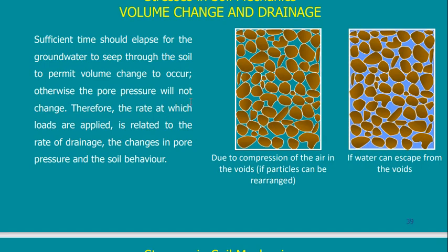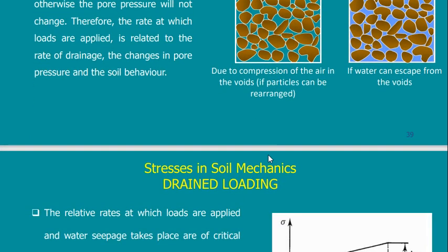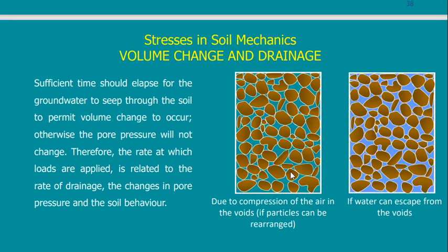now we need to understand what is compaction, because it will be one of our lectures. Compaction means that I'm trying to condense the particles, make them very close to each other by expelling water. If I expel the water, it will be consolidation. If I expel some air, it will be just normal settlement. But expelling water in sand is also settlement, because it will be very rapid expelling of water. But expelling water in clay will take time. In this case, the definition is changed from settlement into consolidation. So consolidation is a settlement, but it takes longer time because the permeability of the soil is very low.